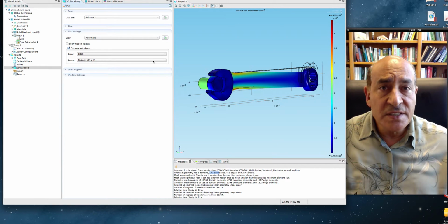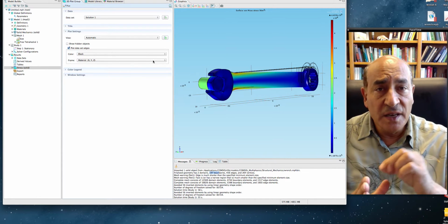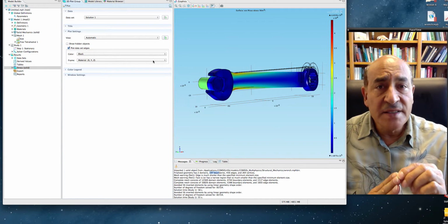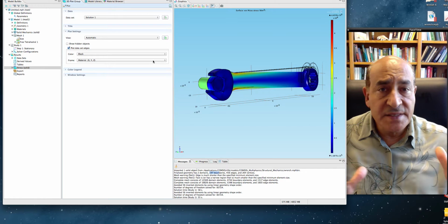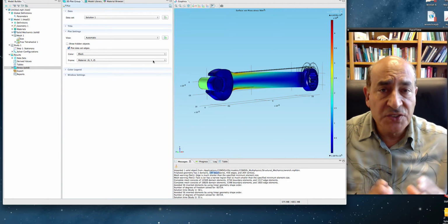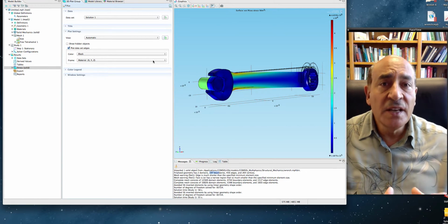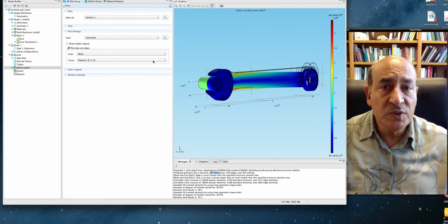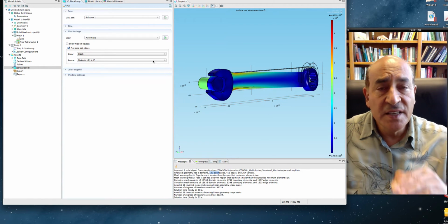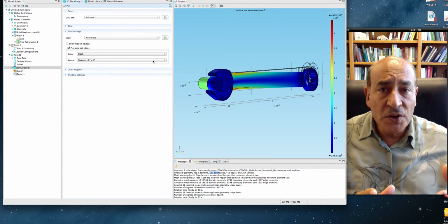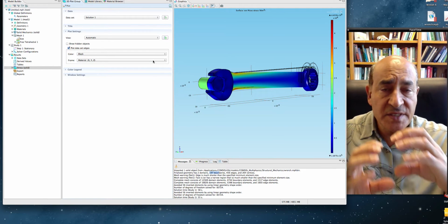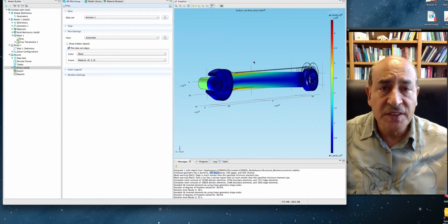The way that it solves for the displacements is by a solver. Each point on the pyramid now, which is a node, has a displacement vector xyz, and it assembles all of these into a huge matrix, and then it solves equations of motion by inversion of a matrix. And the inversion process, you can imagine if you have a very large matrix, it's either direct inversion, which means that it solves everything at the same time, or indirect, which means that it takes a little piece of the matrix at a time and then keeps doing iterations.